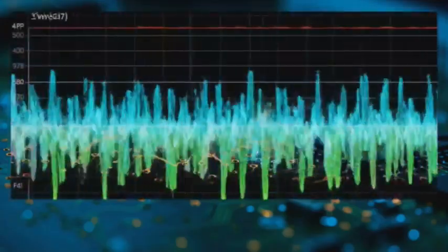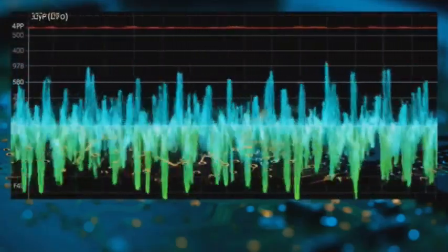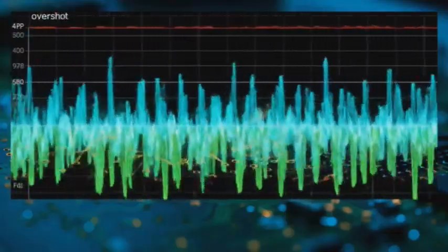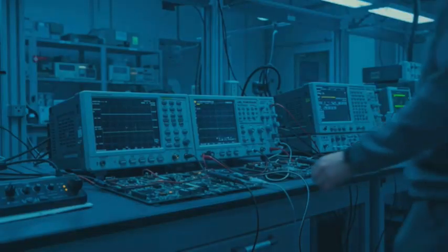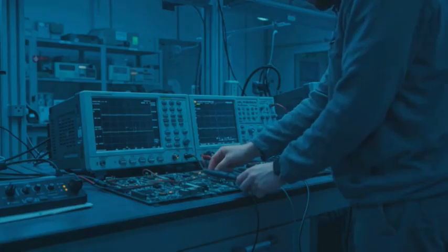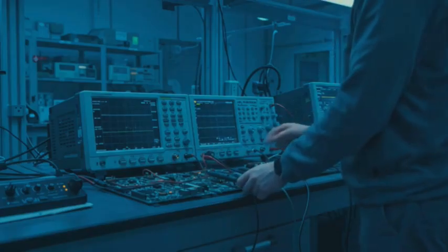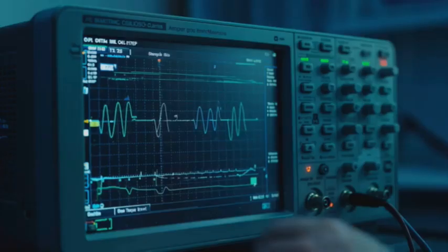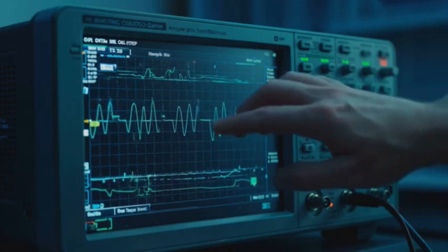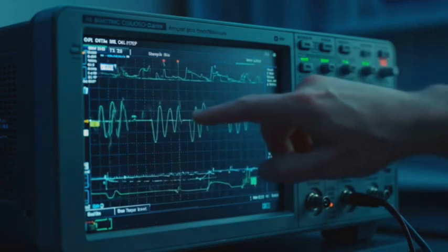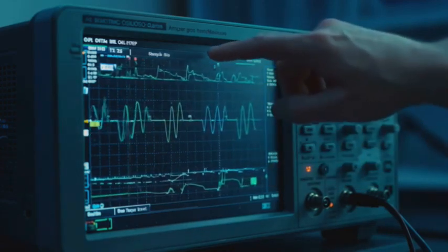We conducted experiments comparing layout techniques' impact on analog performance, RF emissions, and susceptibility. Another experiment series analyzed digital communications, examining trace spacing, grounding, and via placement effects on noise.